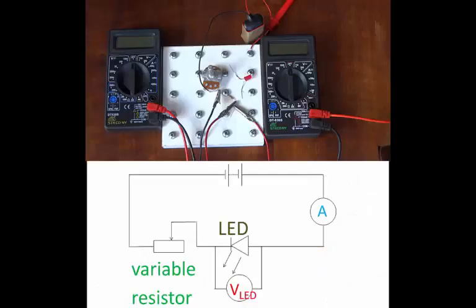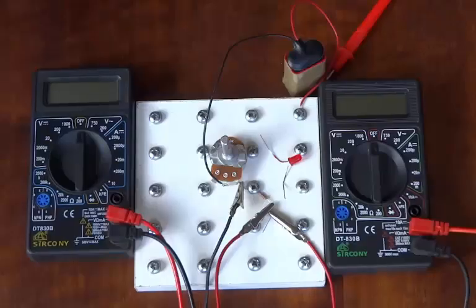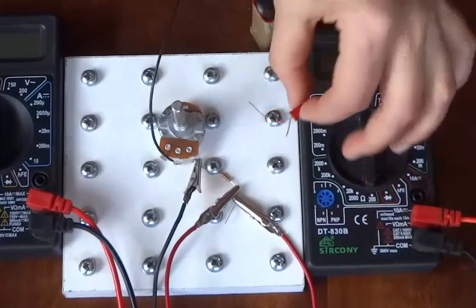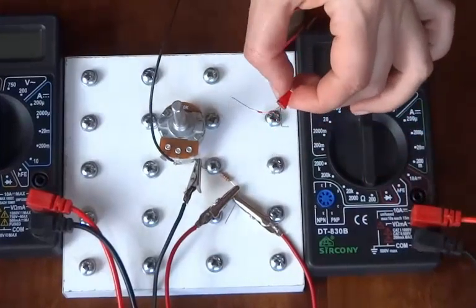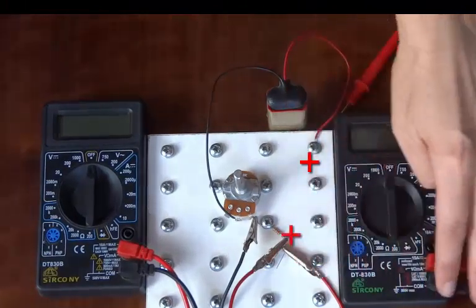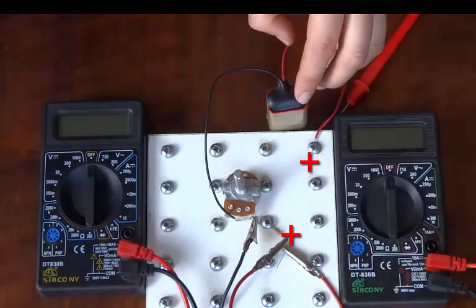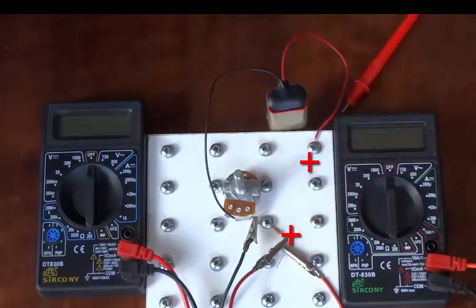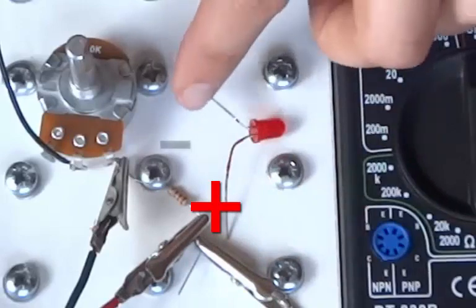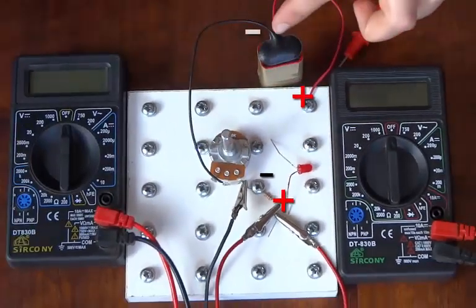So we're going to use the same circuit that we used before, except that instead of having the 2K2 resistor in that position, we're going to put an LED in that position. So all we need to do is to remove this 2K2 resistor and put in the LED. But we must make sure that we put the LED the right way around. We can see that this side of the circuit is connected to the positive terminal of the battery. And so we need to have the long leg of the LED connected there, and then the short leg there, which is then connected to the negative terminal.